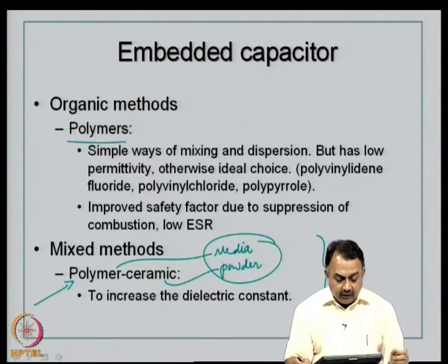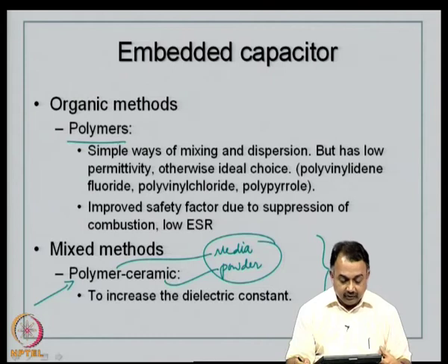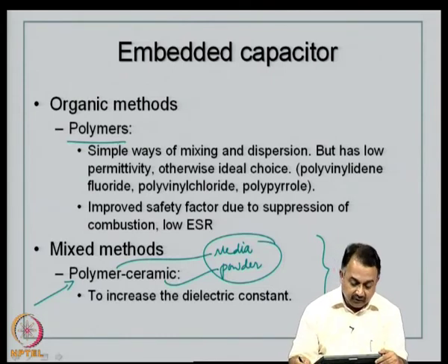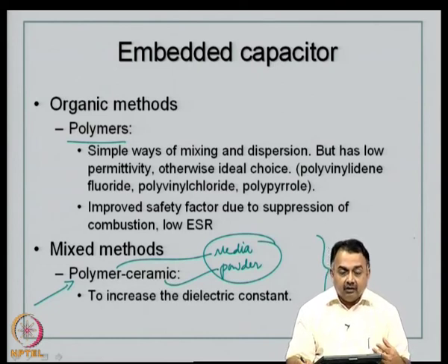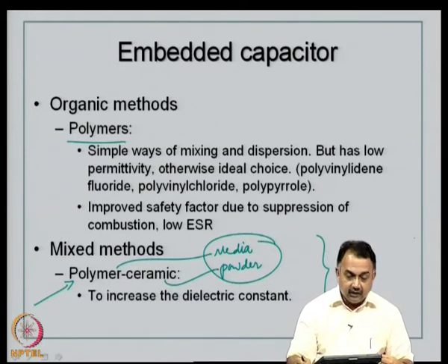So, using polymers could be a solution in terms of large area manufacturing, but if you want to synthesize your own capacitor, the polymer ceramic method is a highly advantageous method, because you know the dielectric constant of the polymer material that you are using, and then you can also formulate ceramic powders based on the dielectric constant, and then your design that requires these values.